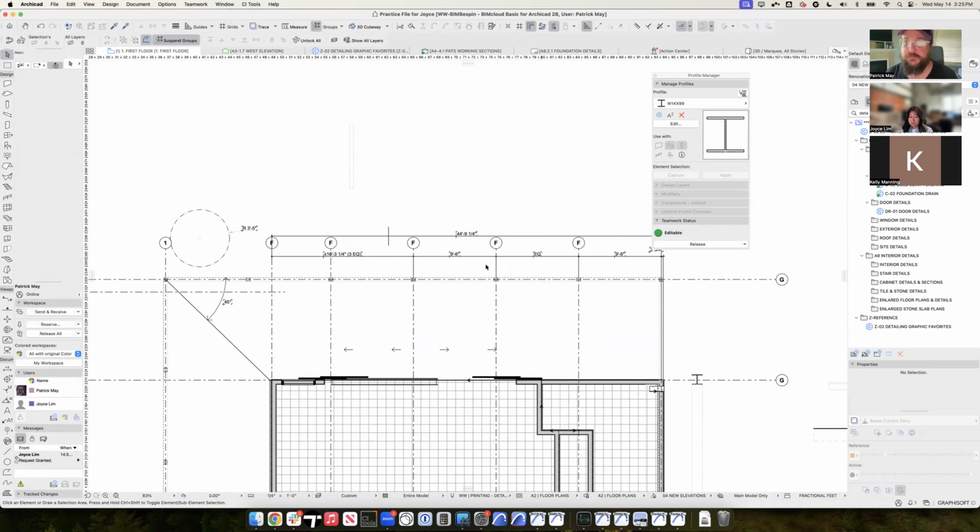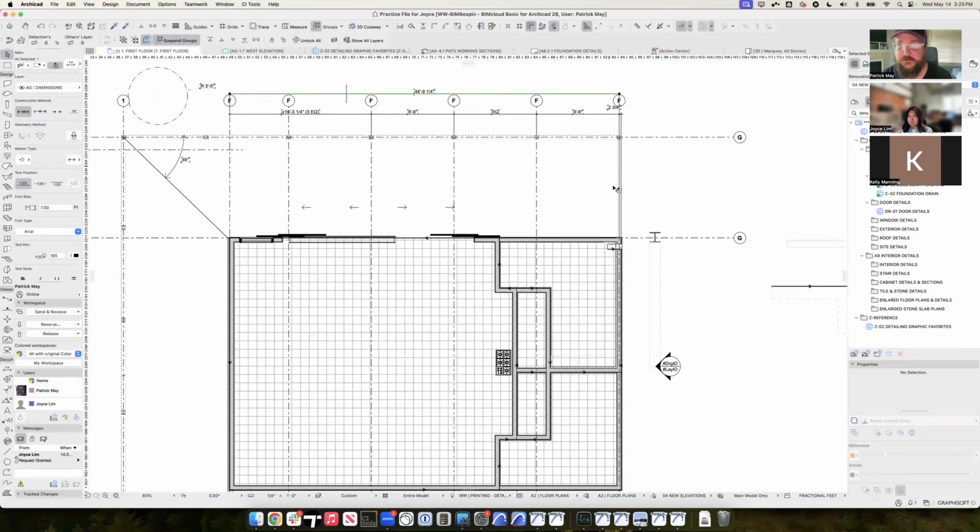It doesn't add up to what the total dimension is because of rounding errors. So dimensioning to the nearest 64th avoids those rounding errors. And 64ths do show up as a big red flag on needing to fix the model.